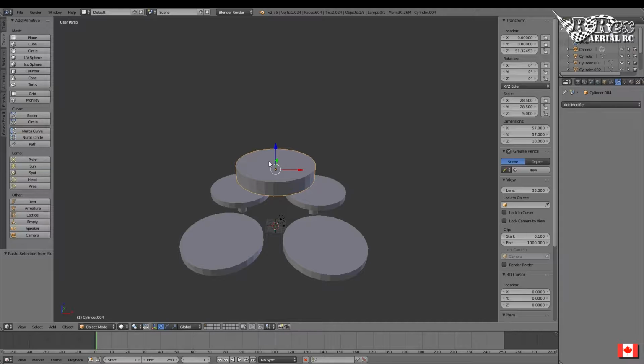You're going to need to take a few prints to actually figure out what your sizes are between your printer doing it in 1 layer or doing it in 2 layers. 2-layer thick walls are a lot stronger than a single layer wall that's extruded thickly, and that just has to do with multiple adhesion points, especially when you're printing with high heat.